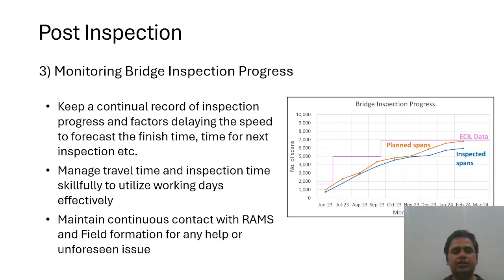The third part is that you also have to monitor the bridge inspection progress. You have to keep a continual record of inspection progress and factors delaying the speed, to forecast the finish time for the next inspection. You have to manage travel time and inspection time skillfully to utilize working days effectively. You have to maintain continuous contact with RAMs, or maybe the field formation, for any help or unforeseen issue. You can have this sort of chart with you